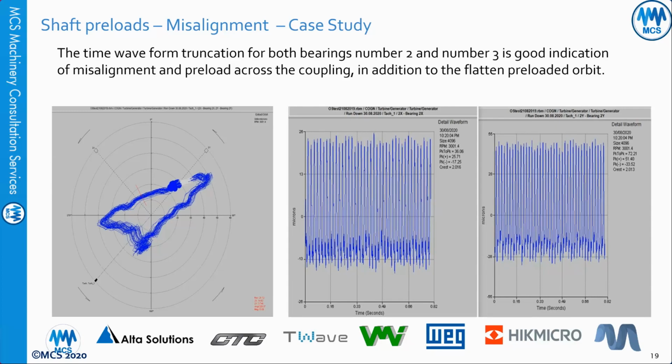Okay. Thank you. This person is specifically relating to example 21. They are saying it seems that vibrations were increasing with the power. Usually, this is not linked to an unbalance or a misalignment. What could be the reason? You mean vibration increasing with the power and not linked to unbalance or misalignment? Normally, it's not the right term. It should be related to load, not power.